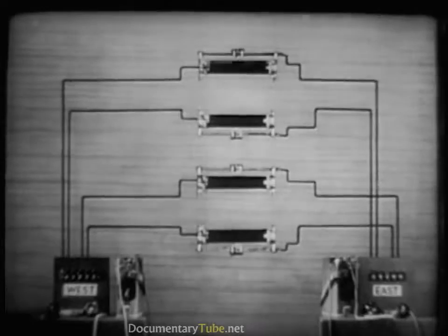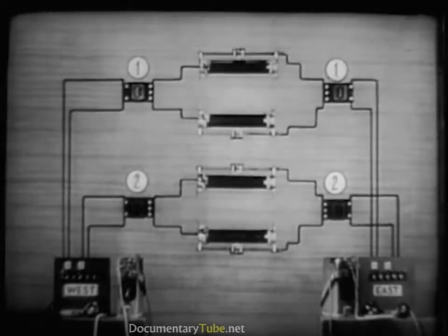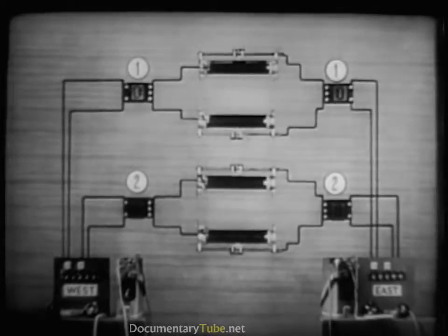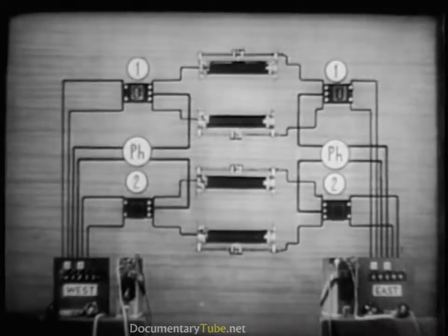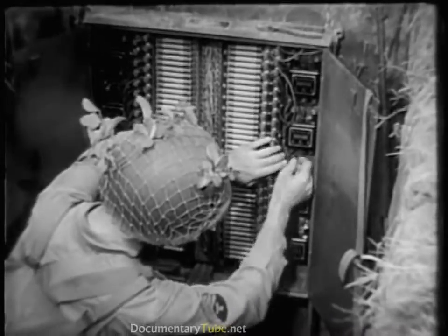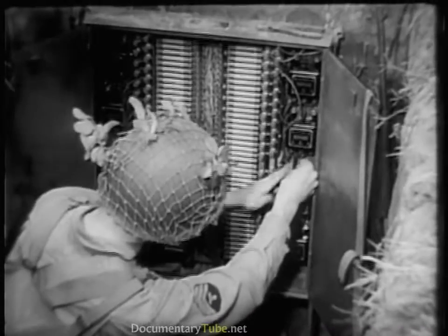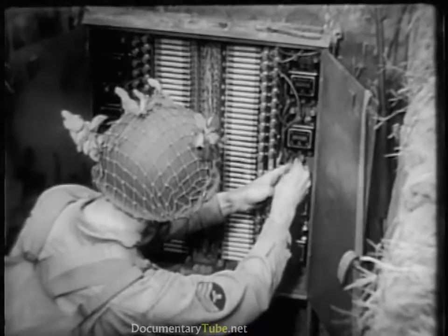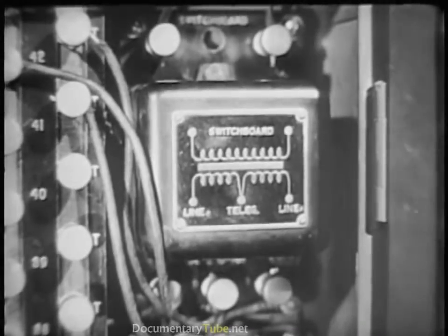The phantom circuit is obtained by connecting repeating coils at both ends of 2 lines. Instead of using 1 telephone line and the earth as conductors, the phantom uses 2 telephone lines. Because simplex and phantom circuits increase the telephone and telegraph capacity of existing lines, the proper use of repeating coils eliminates the trouble, danger, and time of laying miles of extra wire.